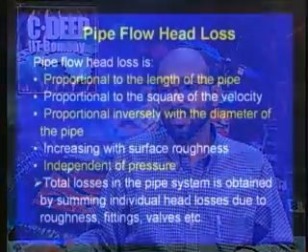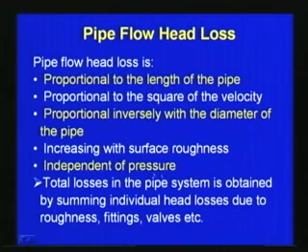We can also see that the pipe flow head loss increases with the surface roughness. So if you use a more rough pipe, then the head loss will be more. But with respect to this relationship, you can see that the pipe flow head loss is independent of the pressure.